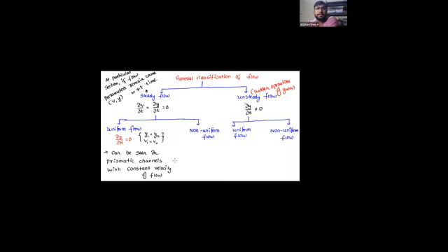Okay, fine. What is meant by prismatic channel? Tell me please. Shape, size, slope remain the same. If shape, size, slope remain the same, then what is the only variable you can observe? Depth of flow. Yes or no? And now when do you say uniform flow? If shape, slope and size remain the same, and now if the depth is also going to be the same, means if the velocity of the flow is going to be the same, you know that shape, size, slope are already constant.